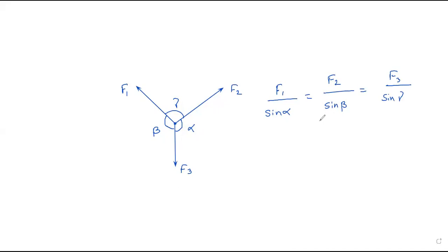The second thing is that all three forces must be coplanar concurrent forces. They should act at the same point. It should not be the case that two forces are acting on a single point and the third force is acting on another point. Then you cannot use Lami's theorem.